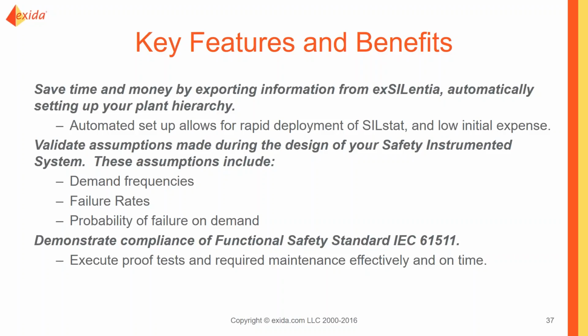In addition, it helps validate assumptions made during your design phase of your safety instrumented system. So again, in your design phase, you assume demand frequencies, failure rates, and probability of failure on demand. This data can give you site actuals that will make your analysis that much better. It will also help you demonstrate compliance of the functional safety standards, in this case IEC 61511. So by executing proof tests and required maintenance effectively and on time, you are keeping up with the safety of your system and complying with the standard.